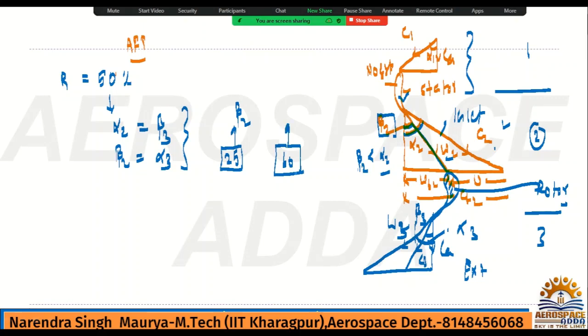So it's very sure that 60, which is the highest angle from the axial, will be alpha 2, not beta 2. In this way you can also understand, because in the statement sometimes you may get confused. Like here, after reading the statement it seemed like beta 2 is given, but if you check the value of the angle, which is 60 degree, then beta 2 cannot be 60 degree. Beta 2 will be less than alpha 2.